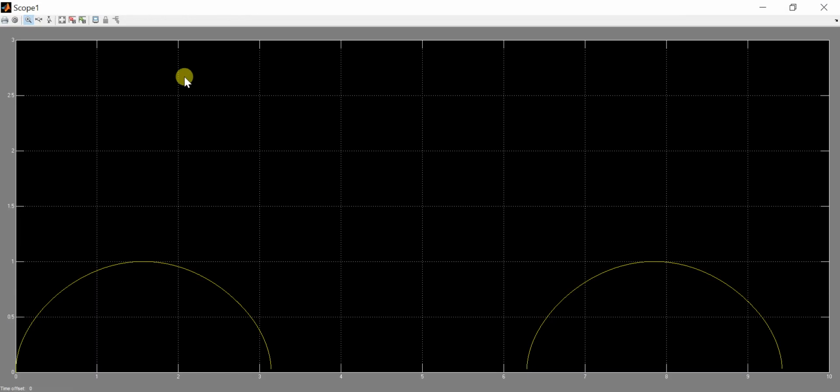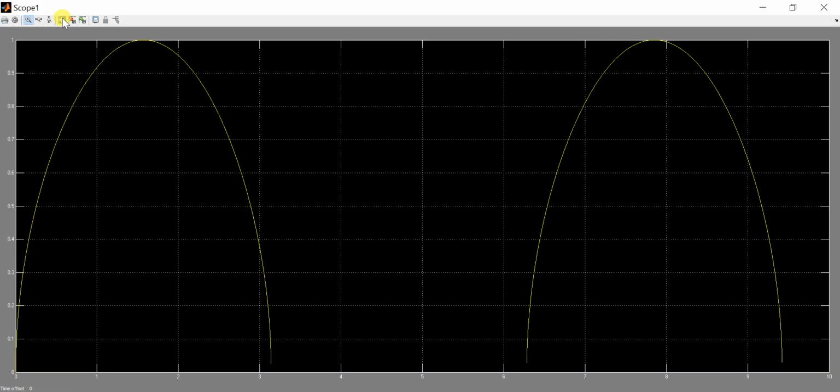see here that it will neglect the negative part and just give the square root of the positive values only, as this scope will not represent imaginary values. So Simulink will skip this and will take only real, positive values, calculating the square root of this particular signal.